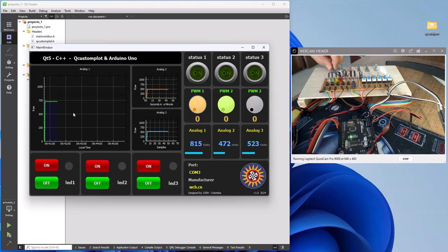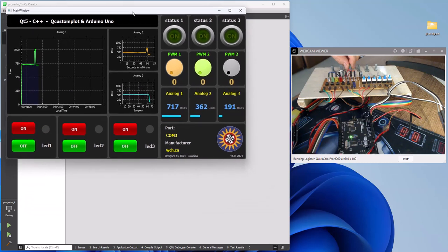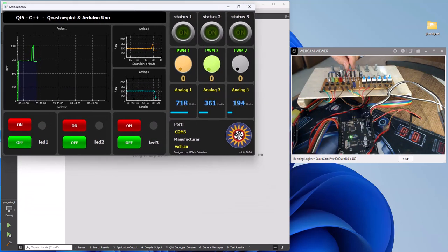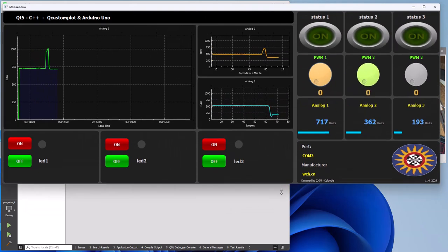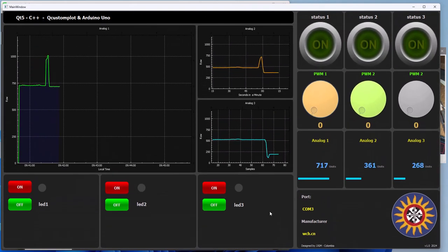Why I use Qt 5 and not Qt 6, there are several reasons. 1. Qt 5 is compatible with 32-bit systems, and nowadays many embedded systems work this way. 2. I like to use very stable applications and that are as much as possible contained in a local file downloaded beforehand. 3. And last but not least, for ease of installation of the Qt development environment, since it is aimed at people with little experience. So let's get down to work.